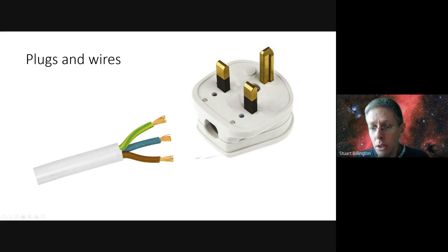Then let's talk about the conducting bit. So we've got this copper wire here. We use copper because it's reasonably affordable. It's not cheap, but it's cheaper than other things. It's a pretty good conductor. It's quite bendy, which means we can coil the wire up into different places, bend it around things. For thin bits of copper, we often break it into multiple strands, like in this picture, but for thicker pieces, we just leave it as one big chunk.